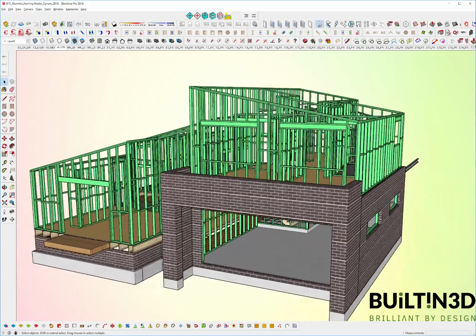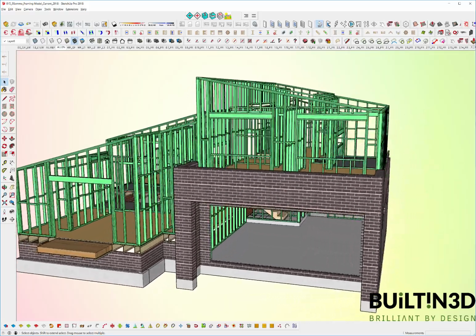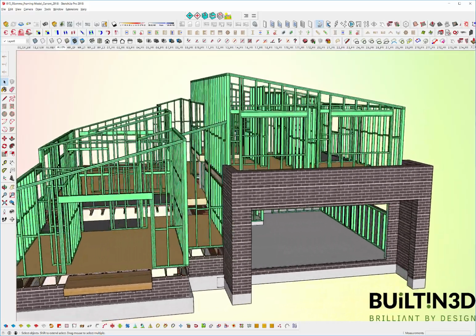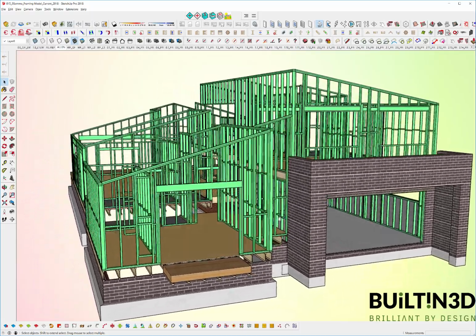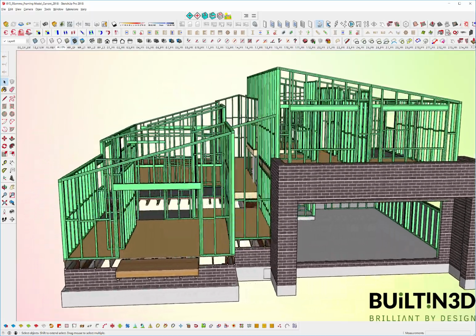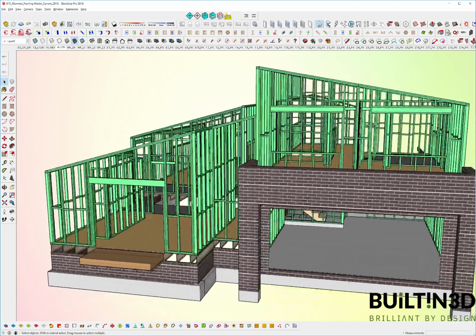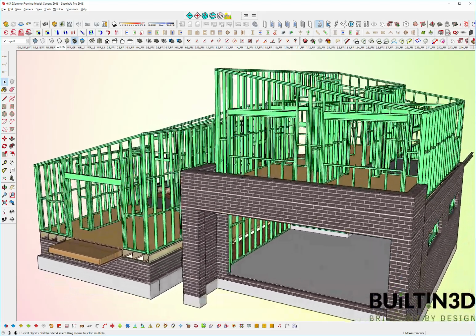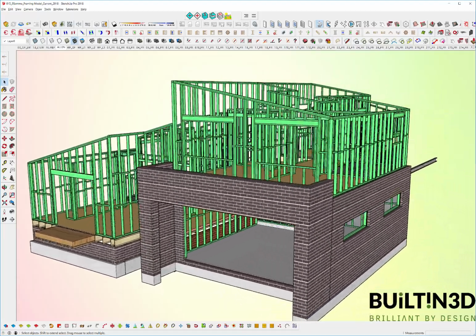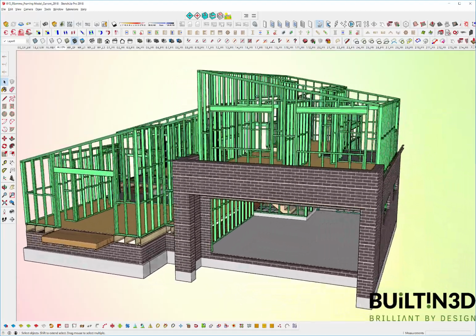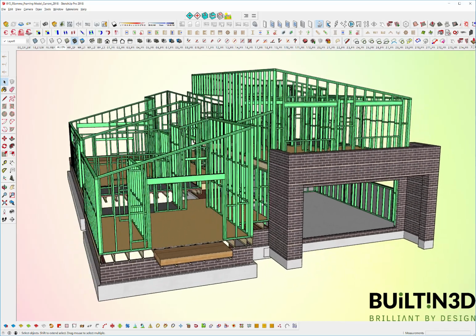Any builder will know that hand cut frames on site are far better quality than those produced typically from a frame and truss company. And it also means that carpenters are able to solve problems on site as they build the frames, rather than have to pull apart pre-made frames and trusses which may have been made wrong. So all the frames for this job will be stick built.